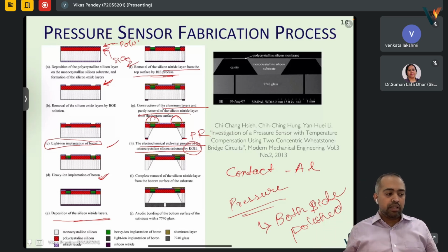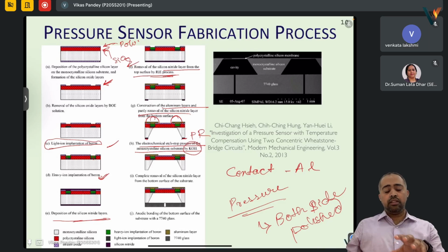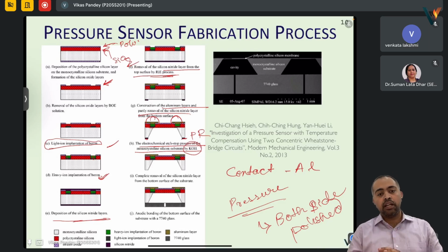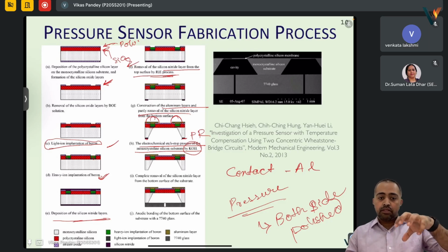So that is a bit tedious process, but due to the present technology, like camera capture as well as the software nowadays that is being used, we can have the complete image of the mask and put it over, and auto alignment is even there. So if we have alignment markers on the bottom, on the opposite side, it will be automatically aligned. And as such, these marks are done.